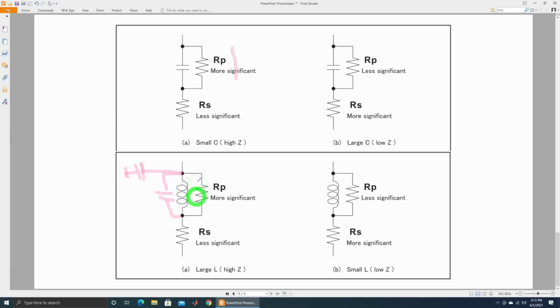So if you measure, for example, let's say your inductor at 1 hertz, you're going to get some value of inductance. But if you measure it at 1 megahertz, the parasitic capacitances begin to kick in. And at some point, the parasitic capacitance and the actual inductance perfectly cancel each other out. You get this resonance point where the impedance essentially goes very high, only limited by the resistive elements of the inductor. At that point, the component switches from being inductive to capacitive. And you can see that sometimes when you measure it. A very important parameter in choosing what component you need to put in your devices is to not resonate at the frequency you're interested in.